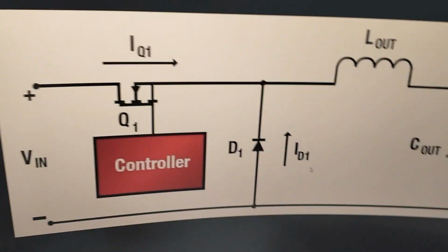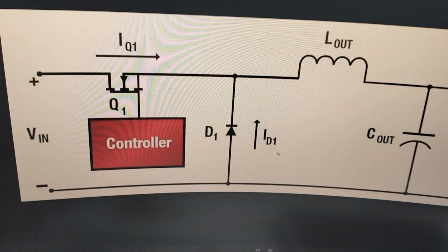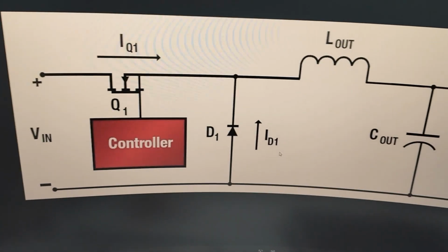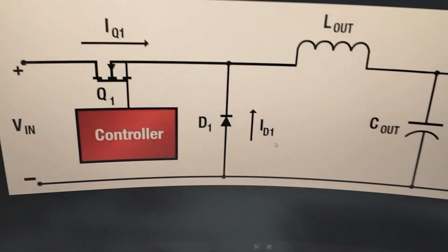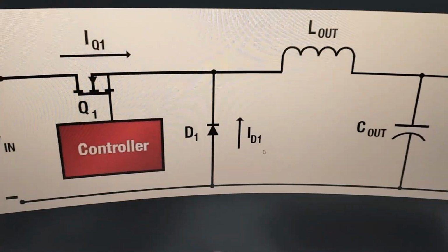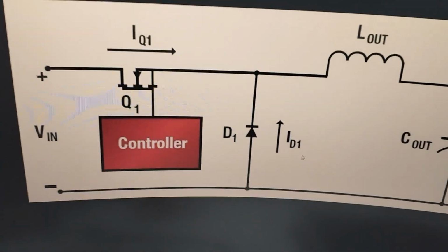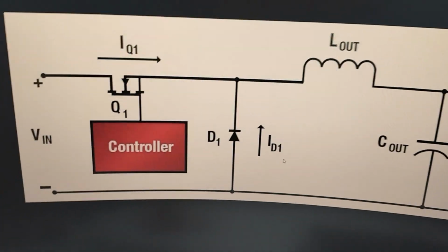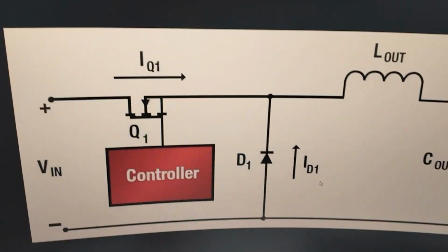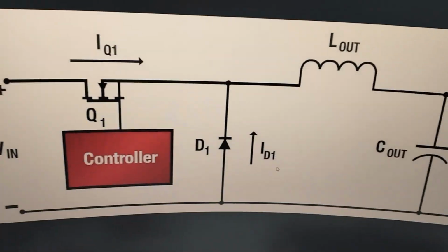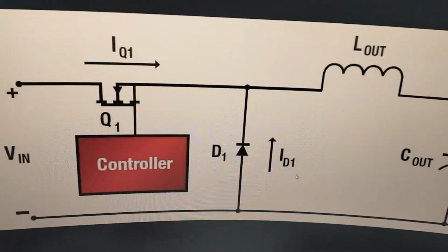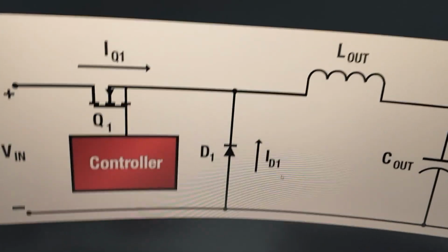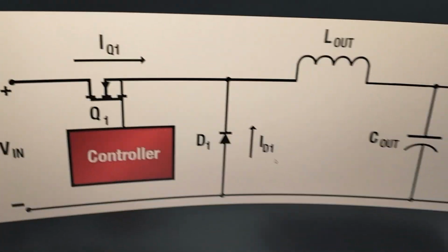So one thing is, if you're in low voltage applications and high current, both of them, low voltage, high current, the thing is that this diode, as we know, diodes, of course, they have a drop. And if you go for standard silicon ones, then yeah, 0.7, 0.8 volts. And if you go for Schottky, maybe 0.3, 0.4, like that. But you can't quite go below 0.3. That's kind of the limit right now.